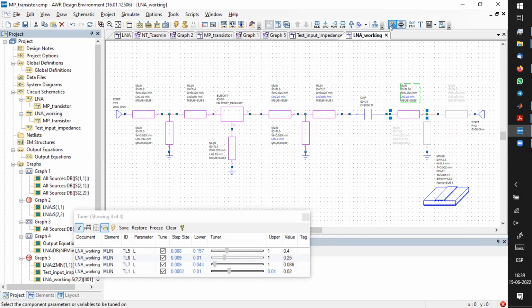So this is now an ideal capacitor, but a MIM capacitor you can actually model like this: in the middle you have the ideal capacitor, and you have 2 transmission lines like this, right? Nobody else saw it. Okay, so everyone is seeing it. And then we can put a very short line. Then you can tune that one. This one is 0.02.